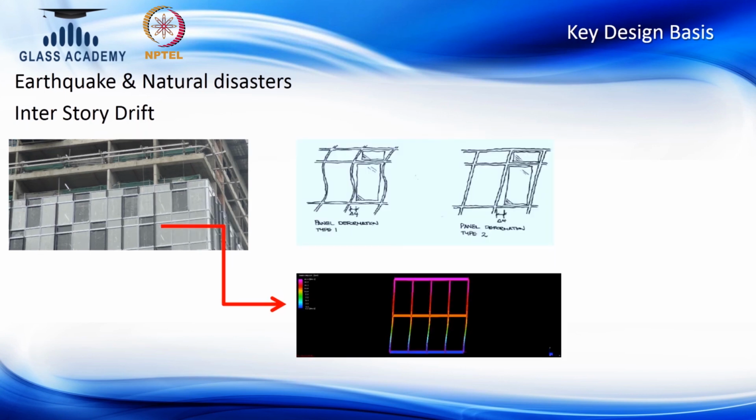Here we could go into a little more detail, with a video showing how this building sway will impact the framing elements in particular. As you can see the building swaying, when the framing changes to red, it is highly stressed. This frame is imposing a lot of loads onto these members when it is swaying. This video is showing primarily this linear sway condition. In this condition, the frame will have more impact relying on the weaker axis bending.